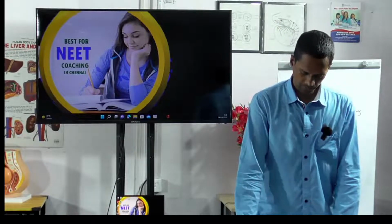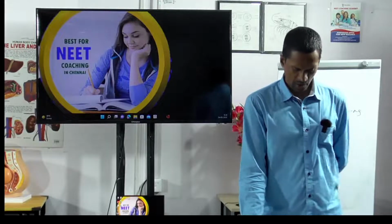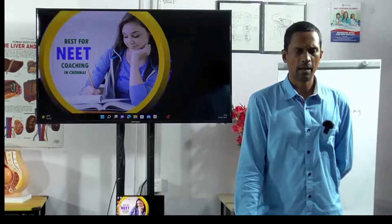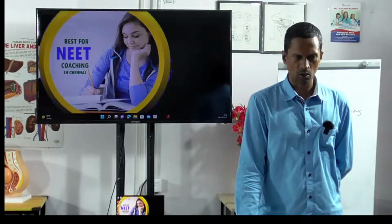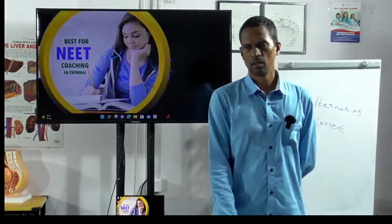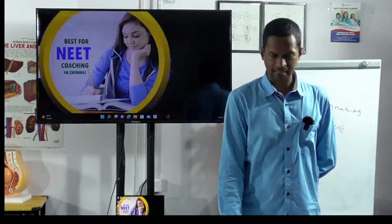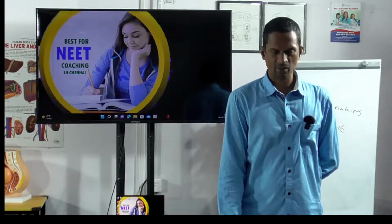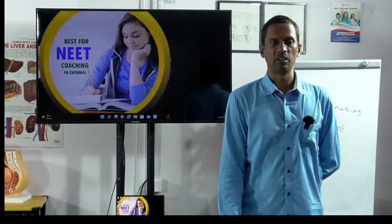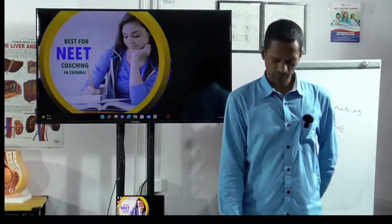Now, transformer. I already told you what step down and step up are. The transformer relation is Vs by Vp is equal to Ns by Np. What is Vs? Voltage across the secondary coil. Vp is the voltage across the primary coil, Ns is the number of turns in the secondary coil, and Np is the number of turns in the primary coil.